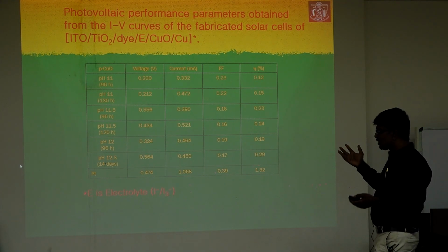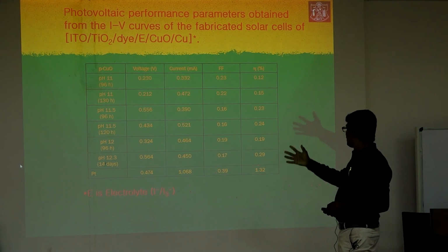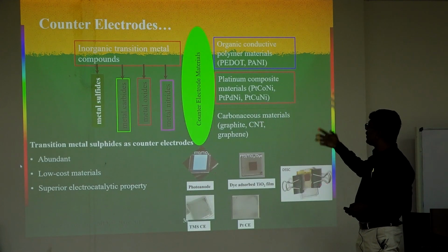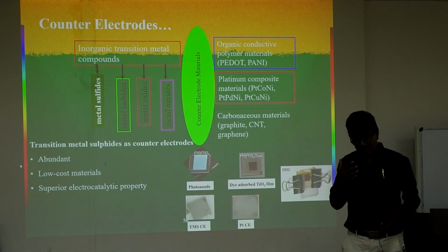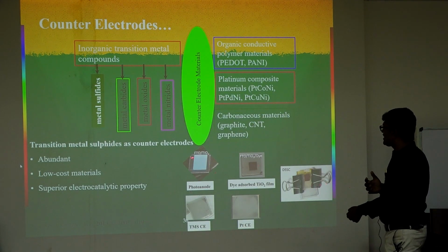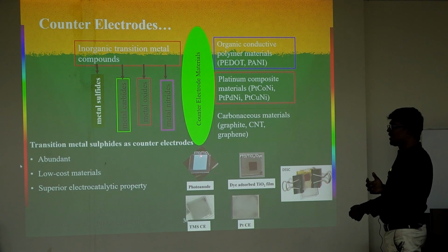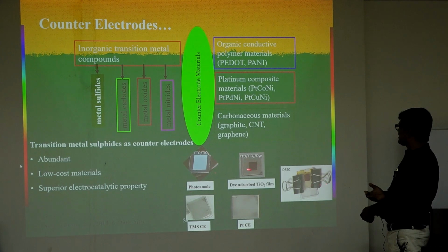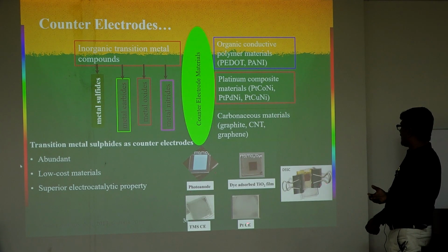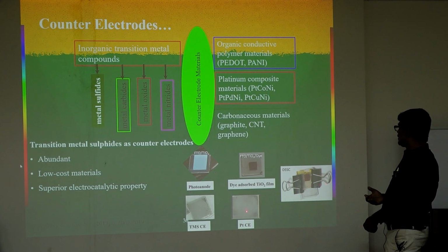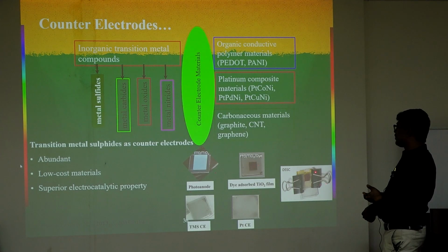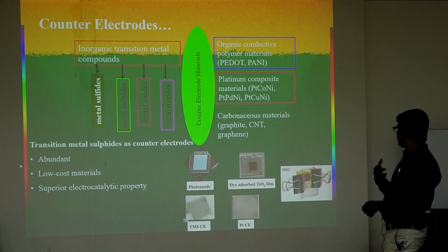So once we do this, we have a very innovative work like this copper oxide. We want to do many materials like this. This is your TiO2 coated glass. On FTO we can coat TiO2, and you can see a uniform coating. This is a dye coated plate on the surface, and this is your platinum coated, transparent one. We make a single cell in a laboratory like this, but we make a big cell also.